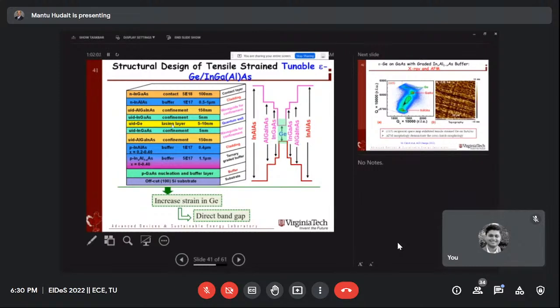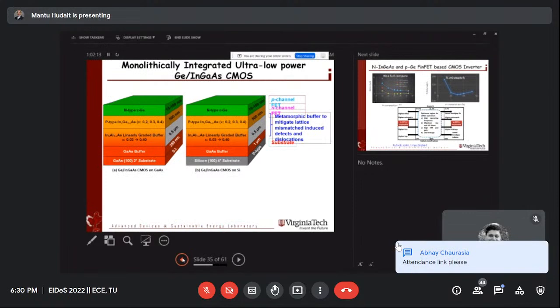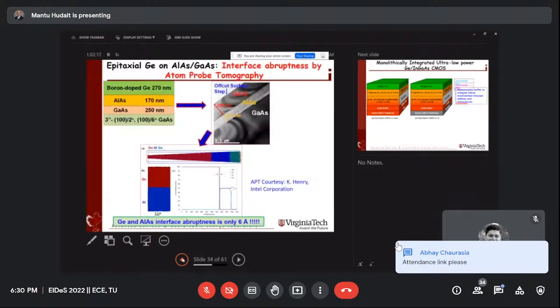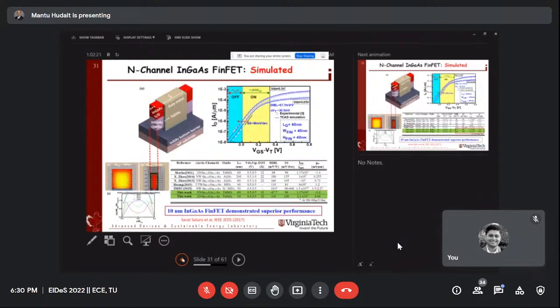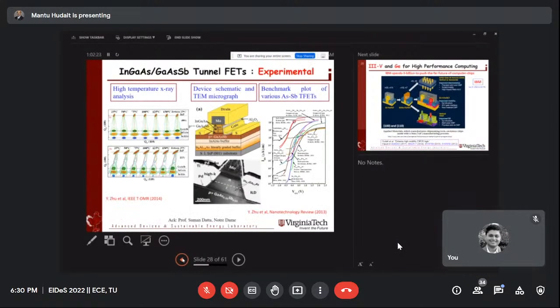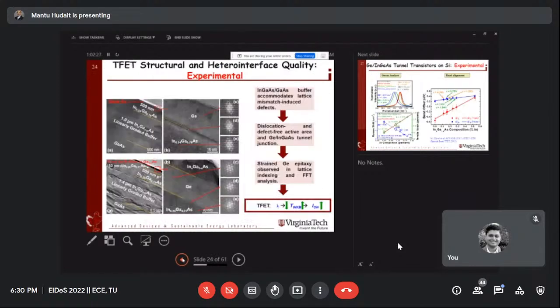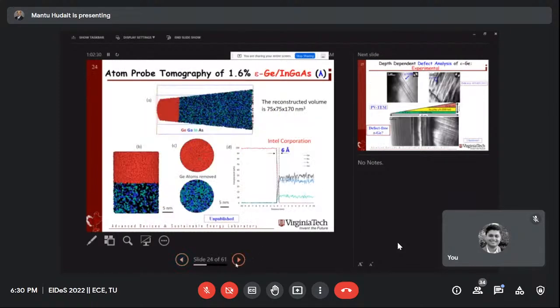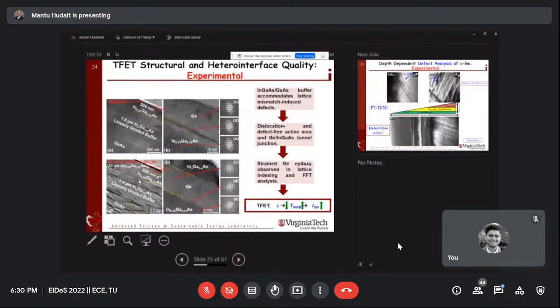The germanium is in a separate chamber. If you put that germanium on the compound semiconductor, maybe briefly I can show you the reactor. I know my postdoc advisor will tell me that I can do it, but I will say with respect, sir, you cannot, because you cannot put the germanium in the III-V chamber, because germanium is a dopant. So right here, Partho, you see here, I'll show you the chamber. See the linearly graded. We do the grade.